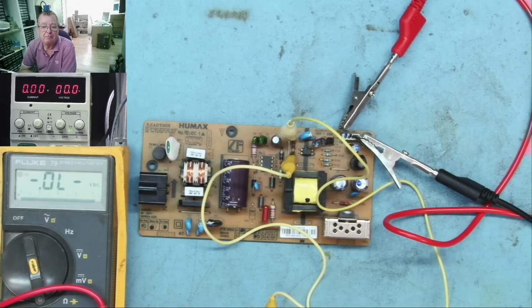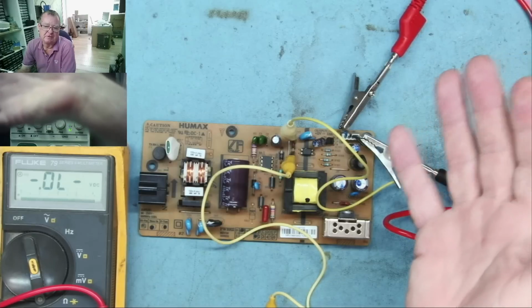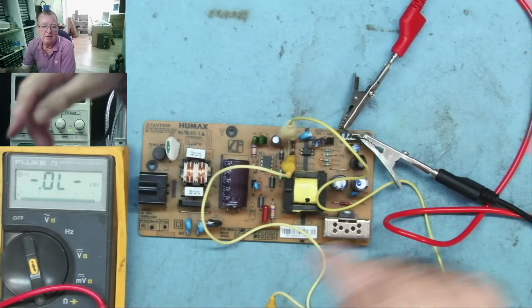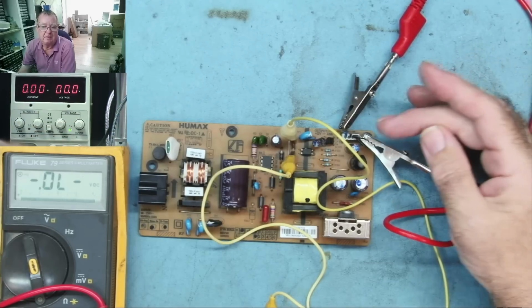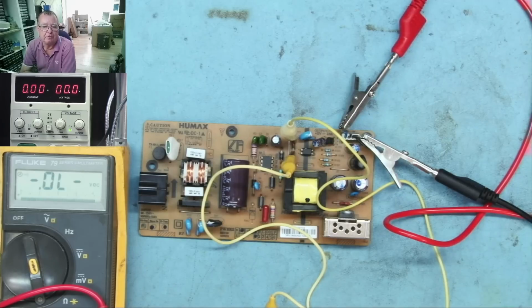Yeah. If you're really not sure, connect your power supply to each voltage rail in turn. Put a bit of voltage in, less than the lowest output voltage. Say you had a 3, 6 and 9 volt rail. Just go to the 3 volts, set it to 3. And just measure on the cathode of the TL431. If you see some voltage there, you know that is the rail which is being monitored. If you don't, just stick 3 volts into the 6 or the 9. You'll soon figure out which is the one you want to test.